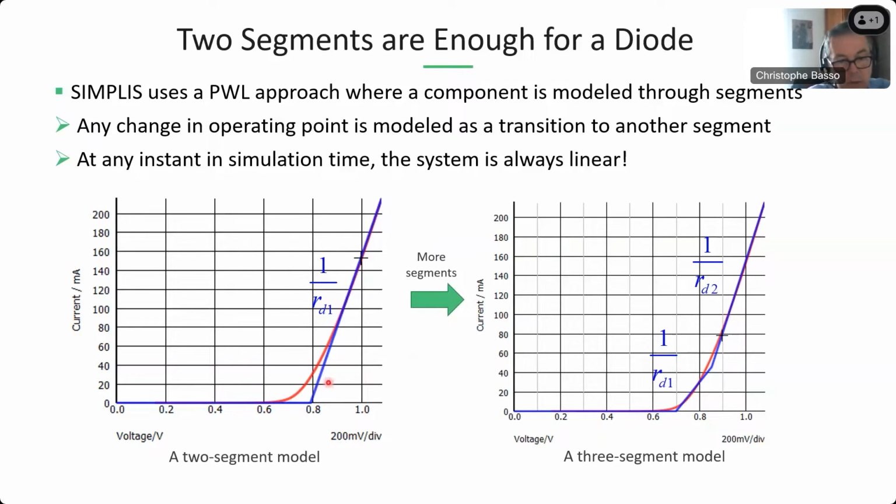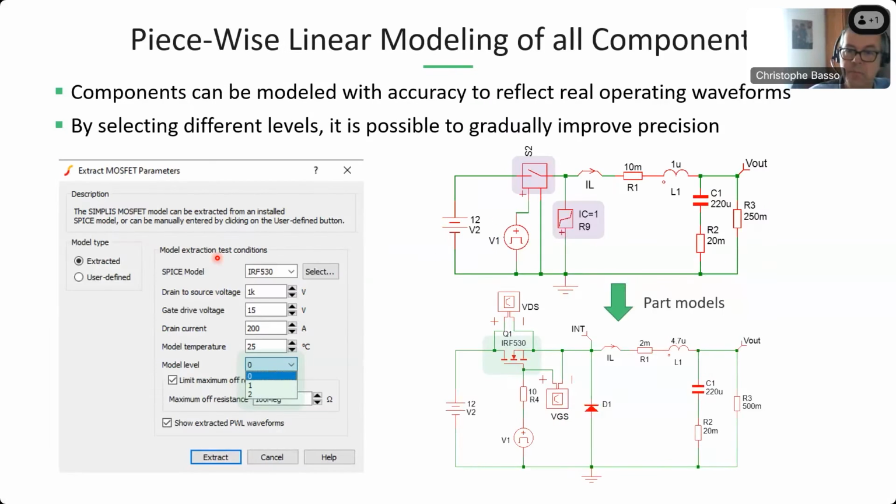And of course, you can transform, for exploration purposes, this model into a simpler one: you start from a few millivolts here and you get a perfect diode. So several models exist to model semiconductors, whether a simple model is enough for a basic quick simulation or a more precise component is necessary to unveil particular waveforms, like determining switching losses, for instance.